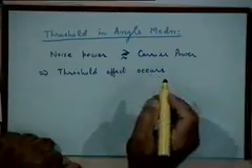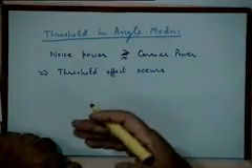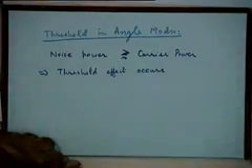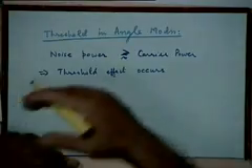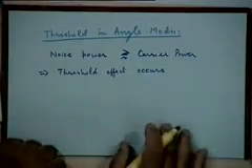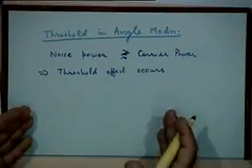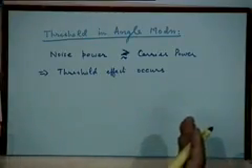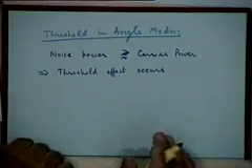So all of you understand what I mean by the threshold effect. That is, the output SNR performance becomes suddenly very poor. It doesn't go along the straight line anymore. Okay, it goes much worse than that. We want to understand this. Since the analysis is going to be much more difficult in this case, we'll just try to qualitatively understand the phenomenon. I think that's where most of the effort will lie.